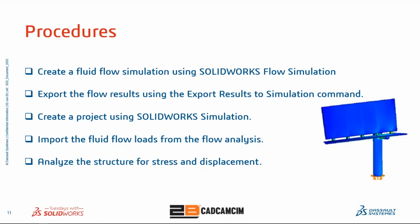This step primes the FLD file, as we will see. The FLD file is the SolidWorks flow results file, where all post-processing data for the flow simulation is held. A simulation study is then created using SolidWorks Simulation. The simulation is set up by applying material properties and adding connections, fixtures, and loads.